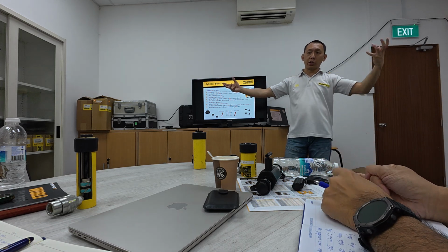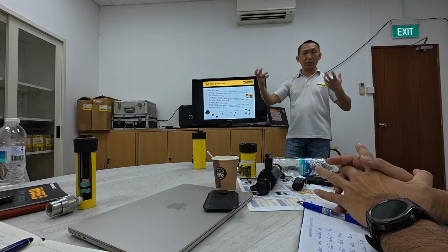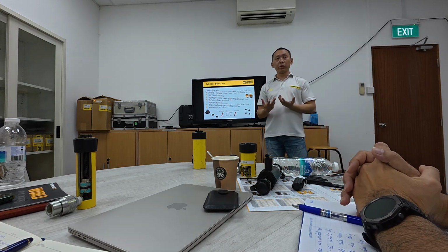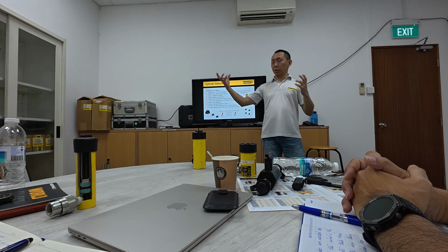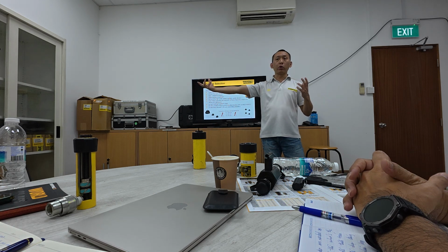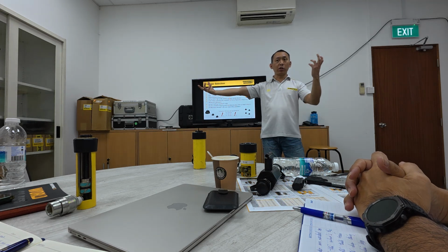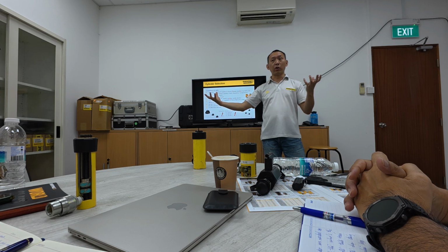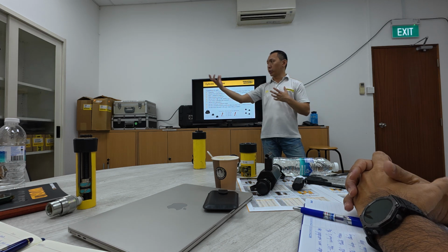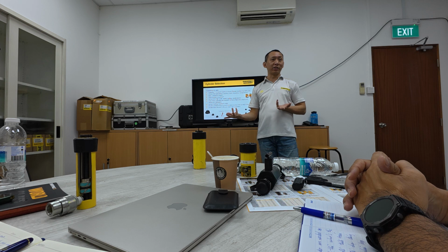So instead of buying 1,000 ton, 500 ton, 200 ton, they might purchase all 200 ton. At this point they put 5 x 200 ton, at this point 3 x 200 ton, so they have a standard cylinder set. Can it be used? Can, because 5 cylinders also add up to 1,000 ton.